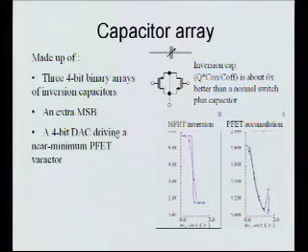That's a good question. There are some answers to that. One is that this is a digital method, so there are some situations where you can't do it. You really can't do it digitally. You really have to have a single analog signal driving your variable capacitance. In that case, you're working with a more traditional varactor, and they're typically pretty nonlinear. So you might be able to get better linearity with a MEMS cap.